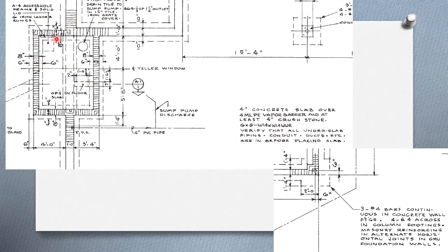Here we have a section A1, 1, and when we have a cutting plane, remember our cutting plane line, this arrow tells me that I am standing here looking in this direction. Someone has taken a slice through here, and I'm on this side looking over here. So on my left-hand side, I will see this wall. On my right-hand side, I will see this wall.